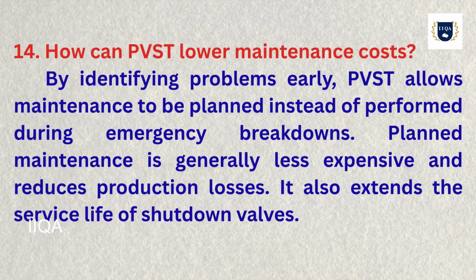14. How can PVST lower maintenance costs? By identifying problems early, PVST allows maintenance to be planned instead of performed during emergency breakdowns. Planned maintenance is generally less expensive and reduces production losses. It also extends the service life of shutdown valves.